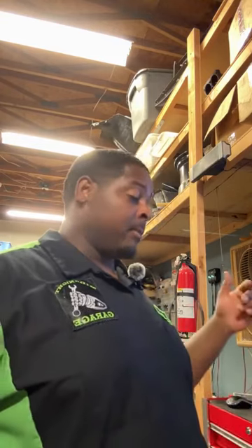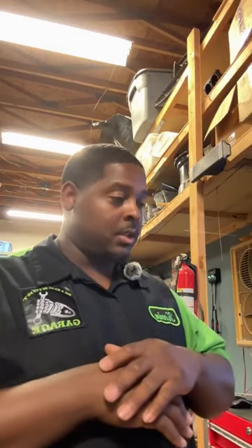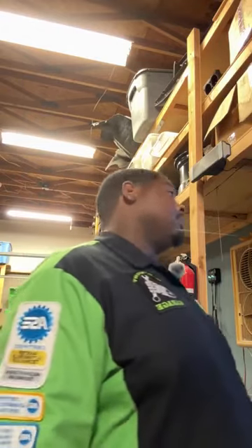However, if your truck is still drivable, I would recommend getting a donor one. If you get it from a junkyard and you don't know the condition of it, that's risky, but if you can get one from a salvage yard that they've tested and you at least know it's running, put it on an engine stand, change out the head gaskets, the valve stem seals, the valve covers, the front and rear oil seals. Make that thing super sealed up and super clean. You can even lap some valves while you have it out. You're going to end up doing both, my friend.